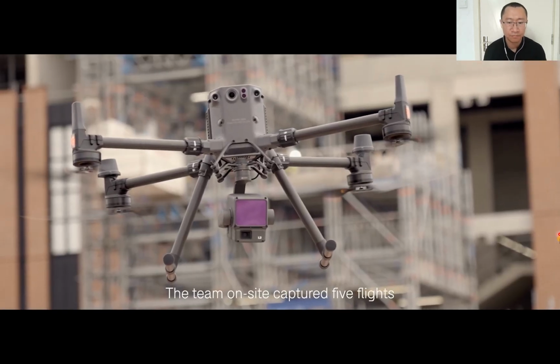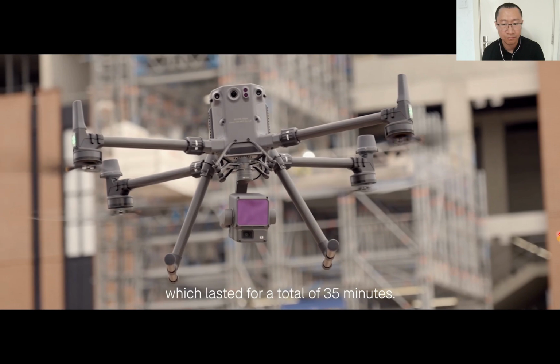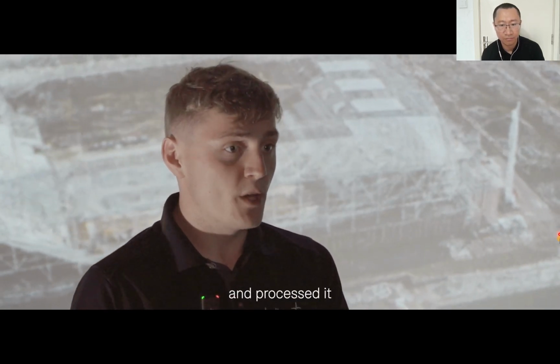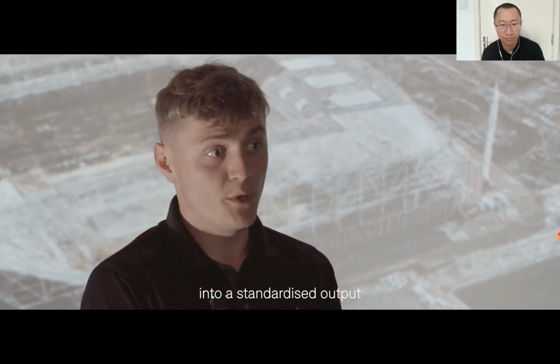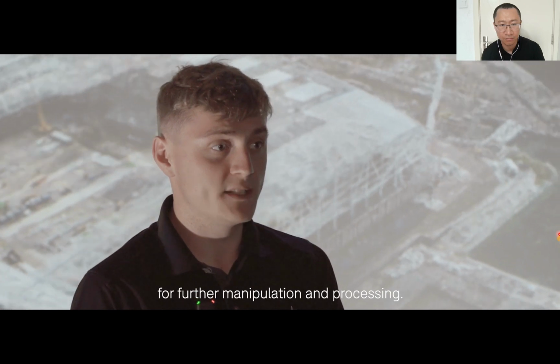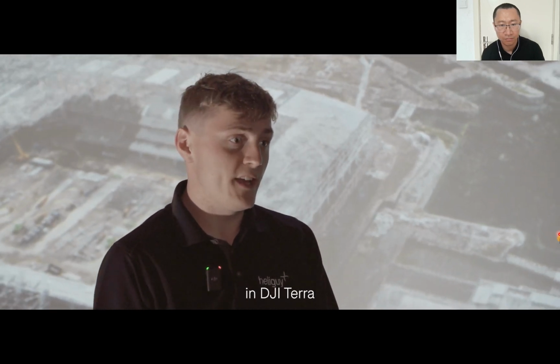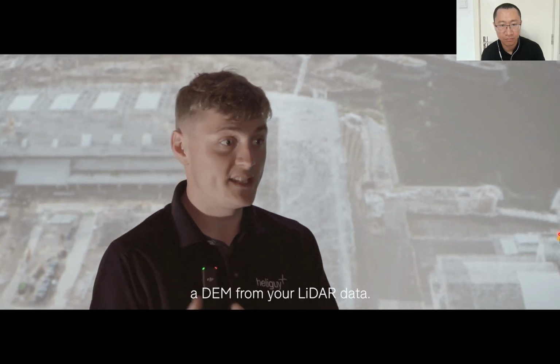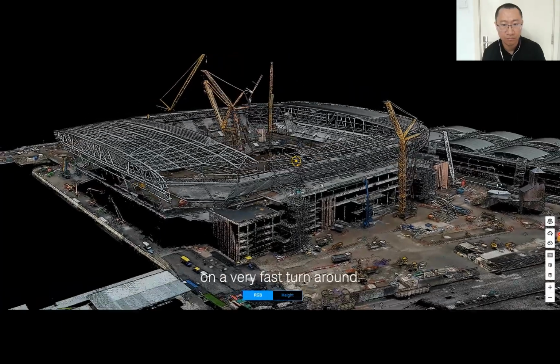The team on site captured 5 flights, which lasted for a total of 35 minutes. They then took the data to DJI Terra and processed it into a standardized output so it could be imported into other software for further manipulation and processing. Some new features in DJI Terra include the capability to classify the ground data as well as produce a DEM from your LiDAR data. Using DJI Terra, we were able to process large amounts of data on a very fast turnaround.